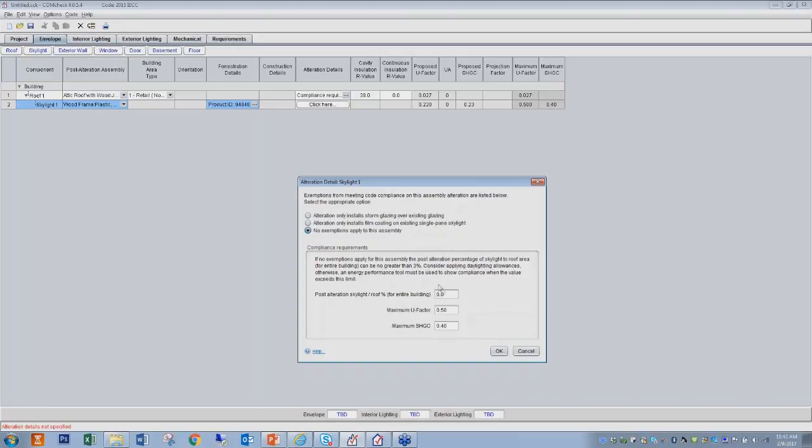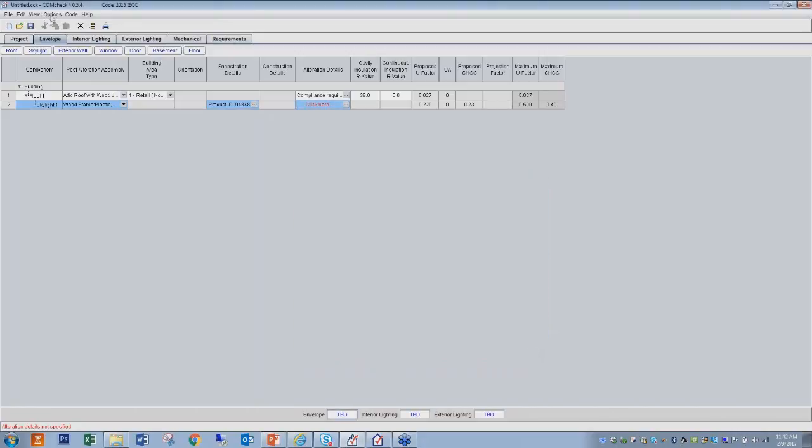If I put 4 here, it's going to kick me out. It won't allow me to do it. So let me hit cancel here, and then we'll go back to it. I can come up to options and click on daylighting allowances and skylight area. Similar to vertical fenestration, when I talked to you about the 30 and 40% threshold, that's where that would apply.